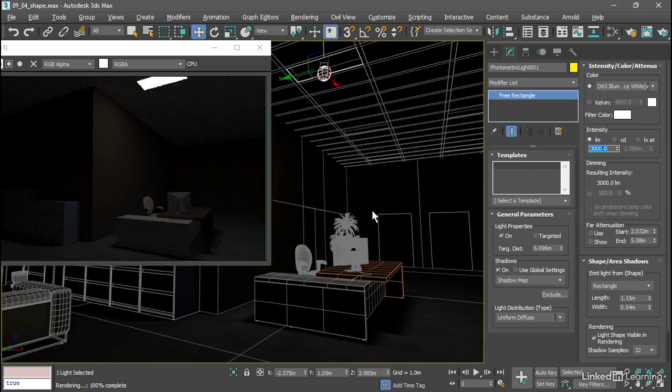We could adjust the rendering with exposure control, but I don't recommend it because we cannot disable the tone mapping of the contrast curve. We'll talk more about this later. If you're rendering lighting studies for architecture and interior design, or just trying to reproduce the conditions of a real-world interior, you'll want to multiply the real-world lumens values by some amount in order to bring the light into a good range for rendering.